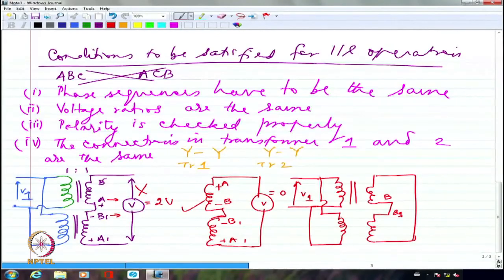If it is a large capacity transformer, because the resistances are going to be really, really small, I am going to have a huge circulating current. So, as much as possible, the open circuit voltages should be close enough. Even if the open circuit voltages are slightly different, I will have a circulating current simply going through this transformer.